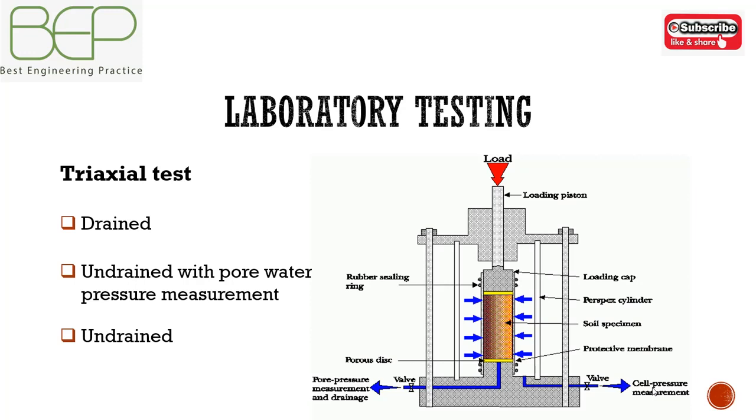and are routinely used to measure the effective strength parameters C' and Phi' of clays. The third type of test is used to determine the undrained shear strength of the soil, which is useful for design of structures for short-term conditions.